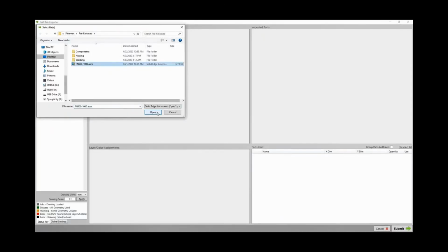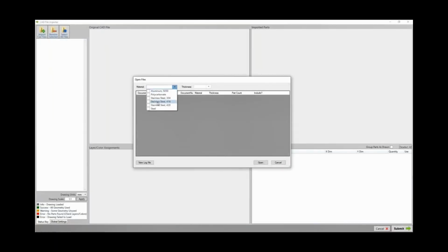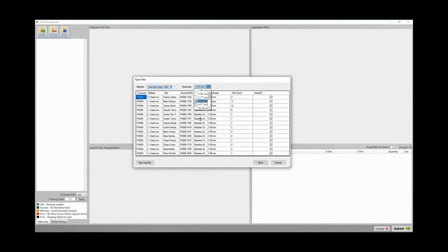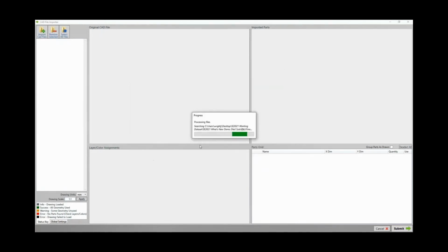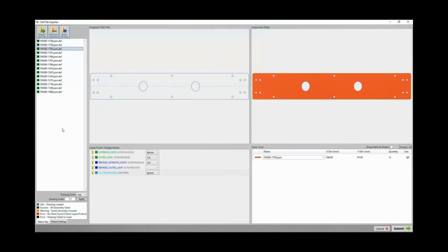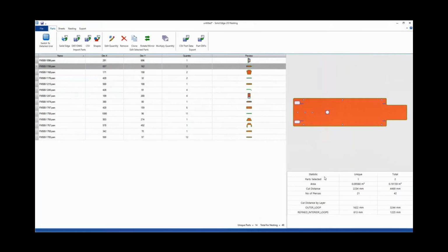And what it does is it looks at the assembly and then it starts to sort the parts by material type and then by thickness. So then we can select the material type that we want for the job. We can also look at other projects that are going on in different parts of the company. The flat patterns are created automatically, saving a lot of time.